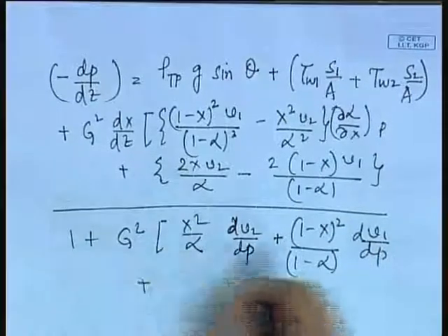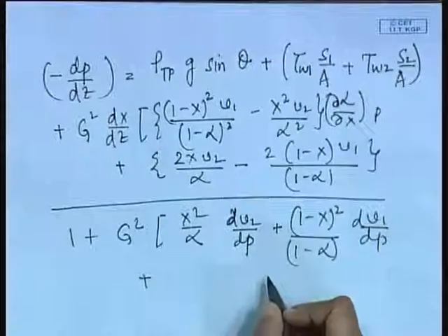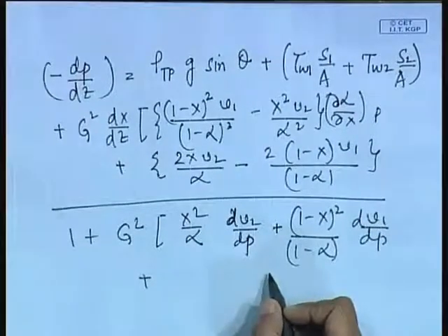And then this denominator term we compared with the compressible flow situation, and said that it corresponds to 1 minus Ma squared, where Ma is the Mach number, which is nothing but the ratio of the velocity of flow to the velocity of sound under the same conditions of temperature and pressure as that of the flow.